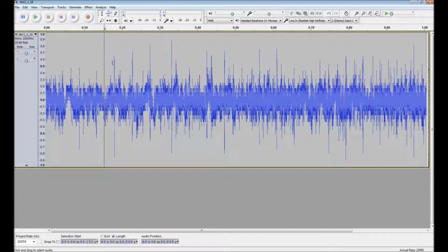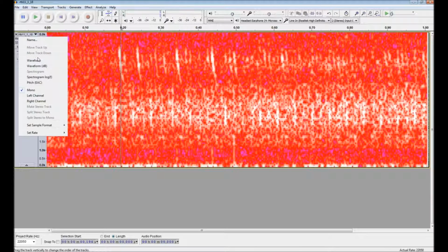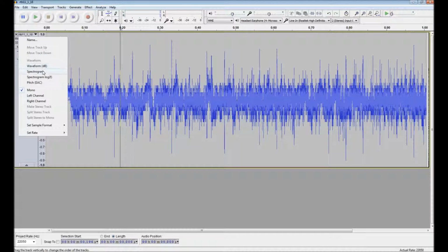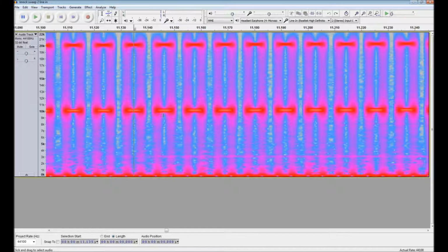This is a real knock. You can see the events going on here. But if we go to a spectrogram, you can actually see it's white. It's a very high intensity. As you can see, the spikes are almost up to 0 decibels. And decibels are from 0 back to negative numbers, not the other way around, on recorded signals. So this signal is not even near to begin being white.